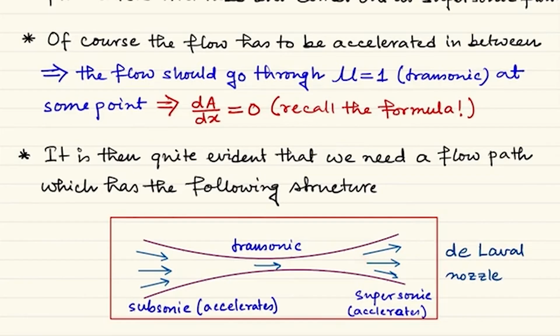And now it actually comes to another part where the cross-sectional area is again increasing, then simply it again accelerates itself, right? And because now this is supersonic flow, finally the flow as a result accelerates throughout the whole nozzle.